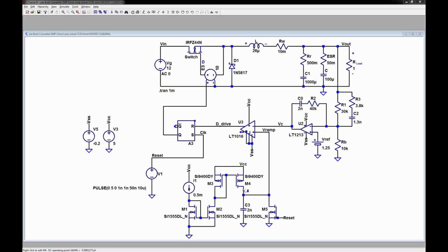Then you will create a current source coming down. So that is the same current source coming down as this one. It should be around 0.5. And when we sim, we're going to check it. Now, due to parasitics, it may be a little bit different, but it should be close to 0.5, which is 500 microamps, or 0.5 milliamps. So that will create the ramp.